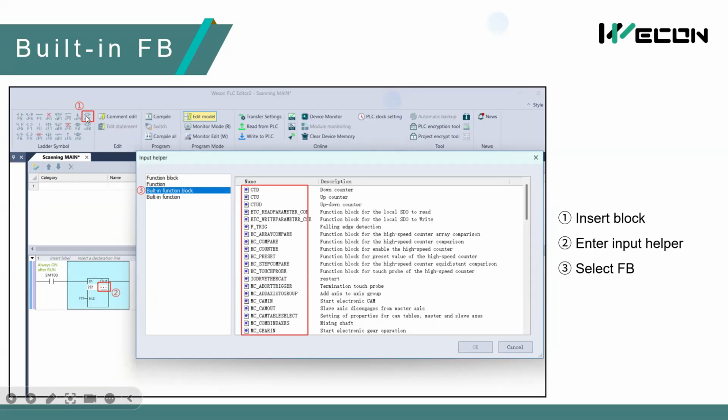We can click these two symbols to insert the program block in our project, and then we click this button, three points, to enter this input helper, and we can select built-in function block or custom function block to use. And the last, here we select the function.